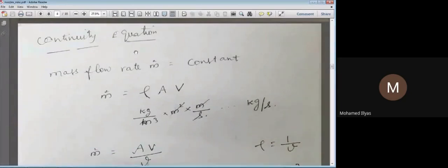That is based on the law of conservation of mass. Whenever a fluid is allowed to flow through a device, its mass flow rate will remain the same. Velocity may change. The fluid will readjust itself to maintain the mass flow rate. Mass flow rate, volume flow rate, and discharge are all the same.